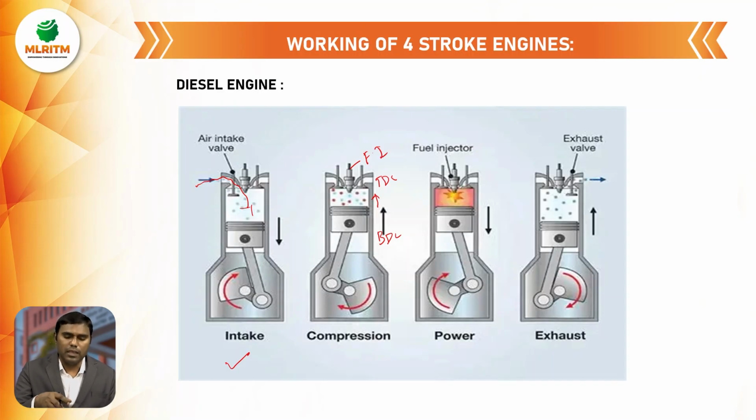Then automatically combustion starts. Here there is no need for a spark plug, because the temperature has already been reached inside the engine cylinder. Whenever the fuel is injected with the help of the fuel injector, combustion automatically starts and the fuel burns at the end of the compression. Due to this burning of the fuel, it produces hot gases. Then the piston is pushed in the downward direction.